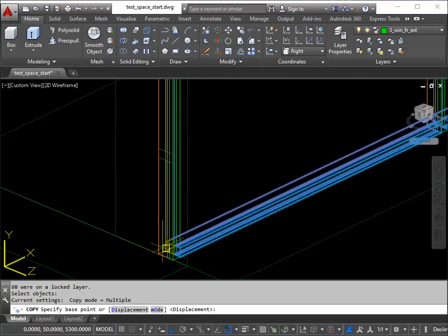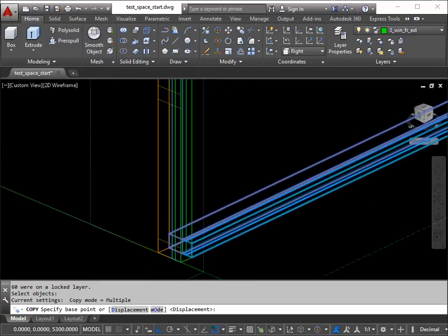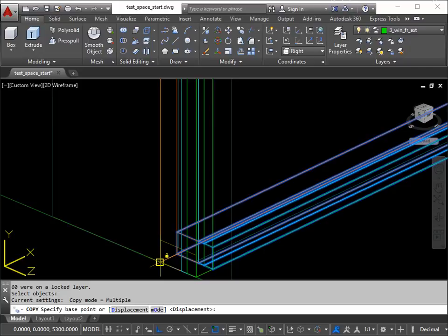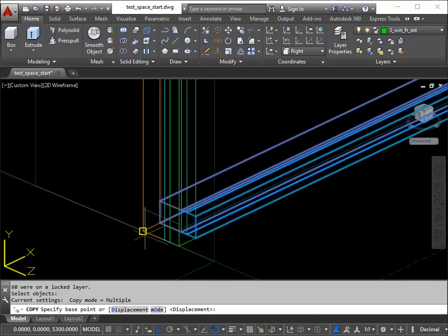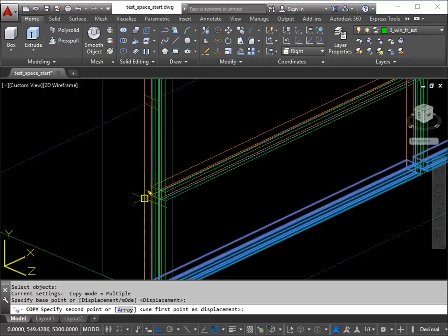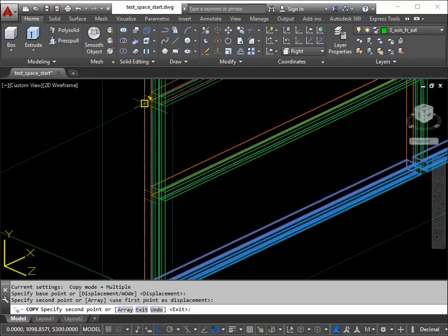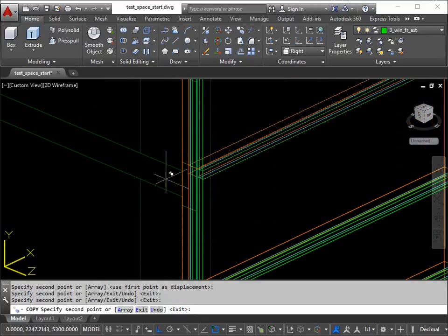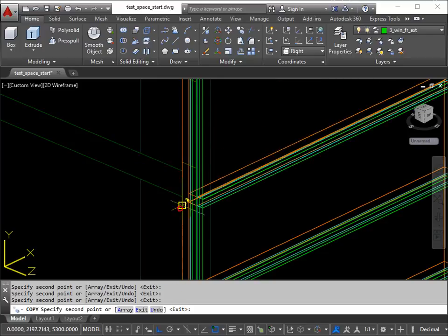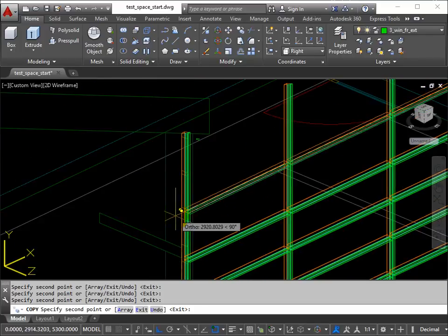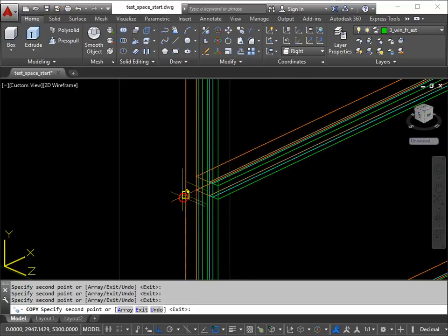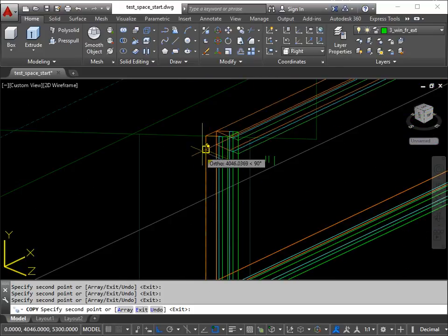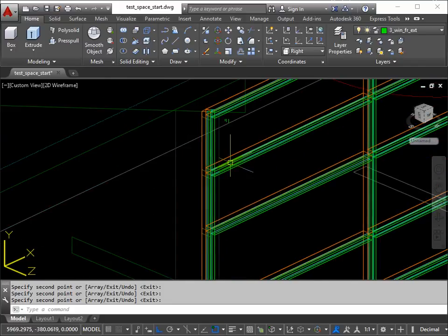And your base point and destination are a bit trickier here, so we're using the 2D section. So look carefully. I'm going to use this as the base point, and then I go up the section looking for the ends of the dull yellow line. Okay, where we've got the light shelf feature coming in, just leave one of our transoms there, and then we've got 3 more above the light shelf, but the top one is going to be a different shape, and that's why we left these here, so that we can stretch these to suit the shape.